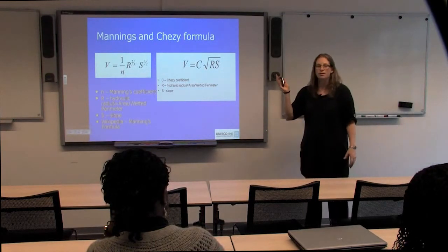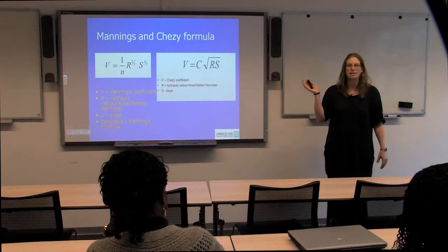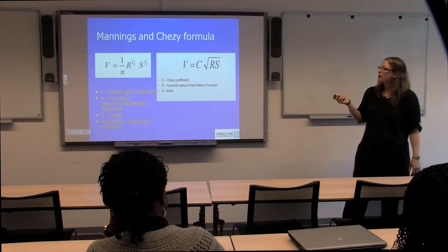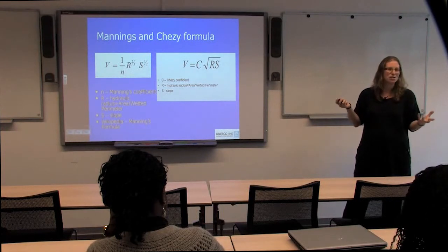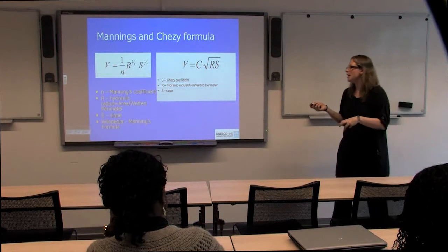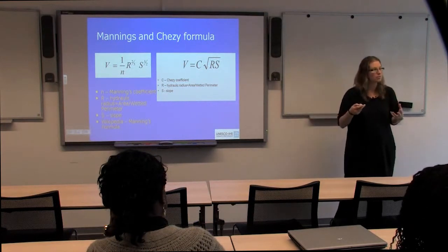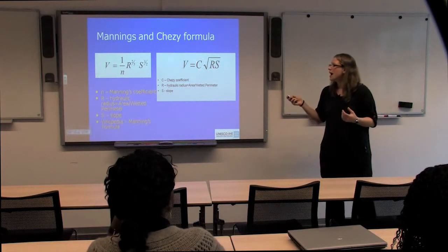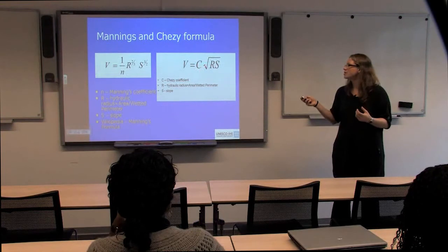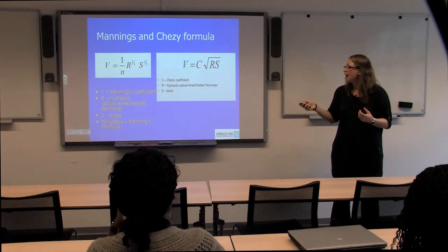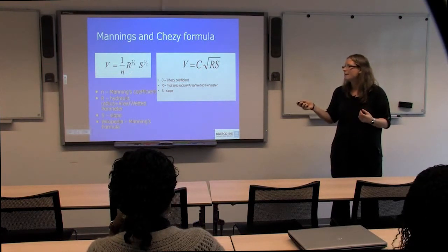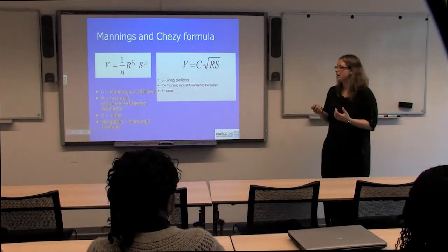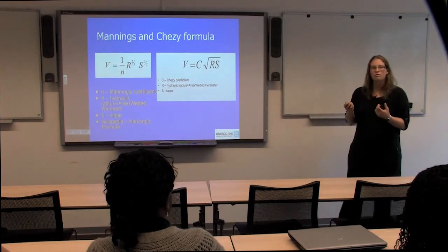You'll probably have come across these equations, Manning's and Chézy. I, being from the UK, tend to use Manning's equation. Here in Europe, they tend to use Chézy much more commonly. And that's just two different ways of measuring friction. So you have the Chézy coefficient, and here you have Manning's n. It just means it's a different factor, which helps you understand roughness.